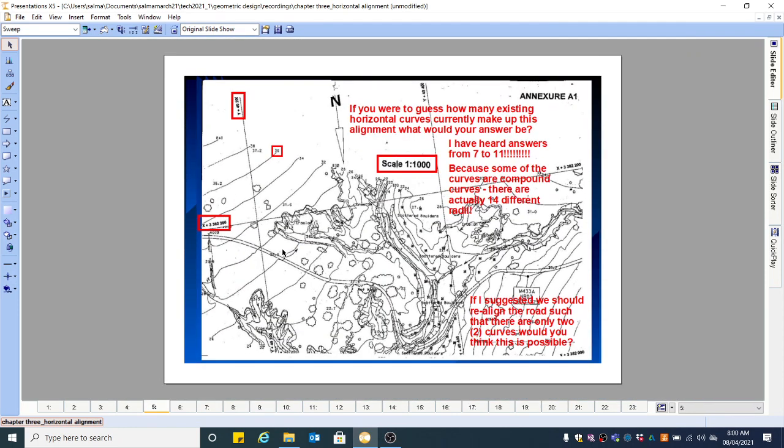Right, so look at your scales, double check that your drawing is to scale, especially when they have grids. Don't ask me what the scale is. If the scale has been given to you, please, it's your responsibility to check that things are to scale based on grids, right? Be aware of the contours and how the ground is falling, the terrain of the layout, right? And the scale is important, the grid is important at this stage.